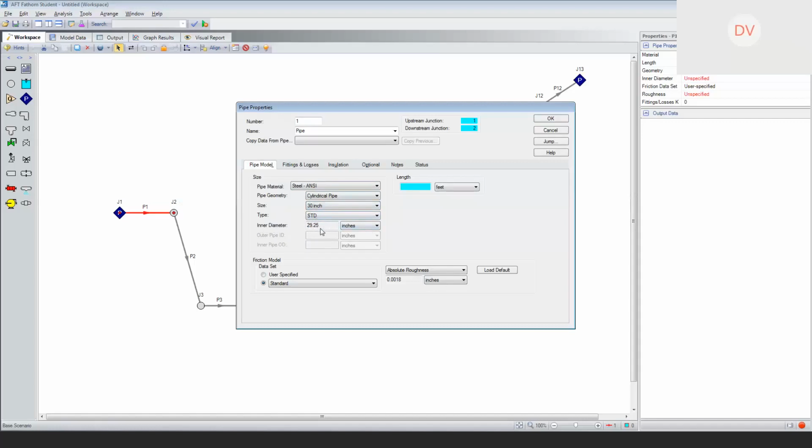For all our purposes, we'll keep this wall thickness for the hydraulic analysis. However, it's extremely important, and a huge part of this challenge is to do calculations for wall thickness and come up with that exact value to be part of your mill order, or what you end up purchasing. So while we do hydraulic analysis around this, it will give us what we're intending out of it, which is our pump requirements. You will calculate your own wall thickness.